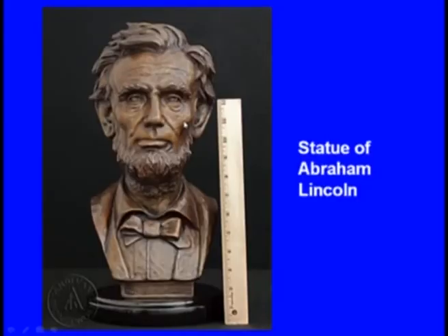Now you can see this is the statue of Abraham Lincoln. Most of the times we see the bronze statues of celebrities. How are these statues made? Initially they make a wax model of that person, and around that they make the compacted medium, a sand medium or a ceramic medium. Later the wax will be melted and drained out. Then they will pour the molten bronze into that cavity. That is how the art castings are manufactured.